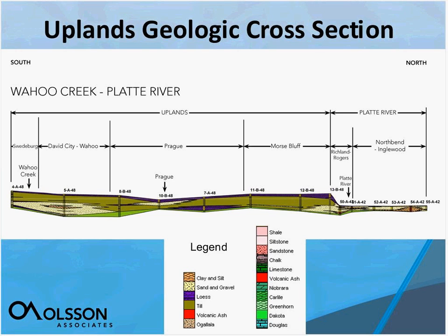So you can see a great difference in these two aquifer types, in that we have these discontinuous sand and gravel units in the Uplands area, whereas in the Todd Valley we have those long, continuous ones. Those are important for understanding what the sustainability of these aquifers are. If they're discontinuous, obviously they have a smaller amount of water that could be pumped from them. As well, these areas in the Uplands have a thick unit of clays on top, which means slower recharge.